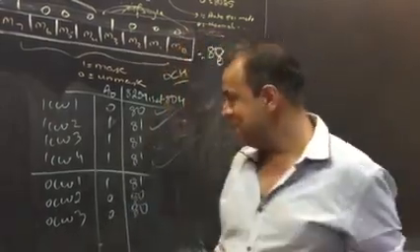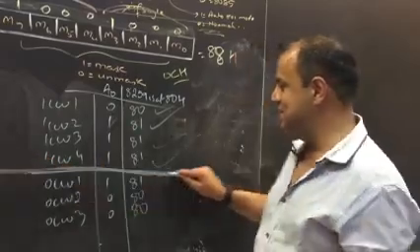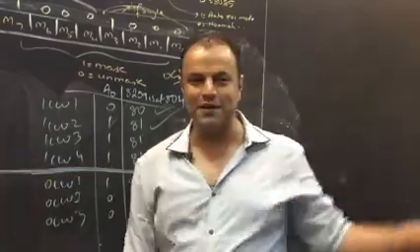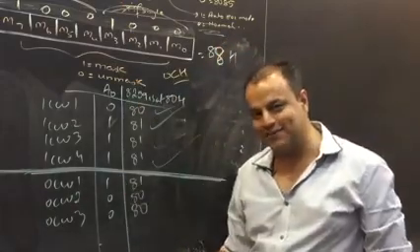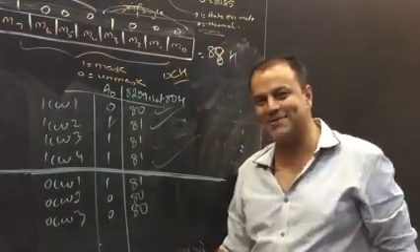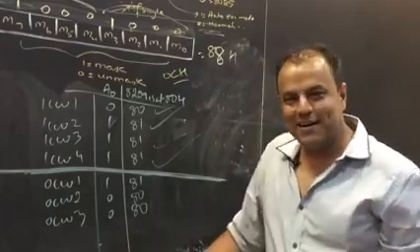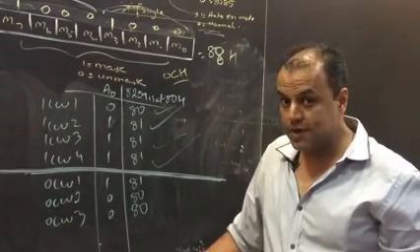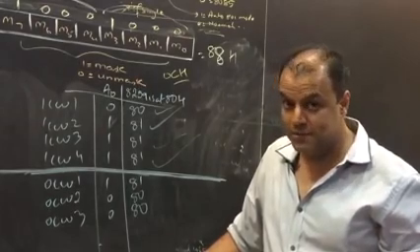Are you clear? Also, once you identified these, ICWs are over. They cannot be repeated. They are out of contention. Now you're left with only 3 commands and you still have 2 addresses to identify them, 80 and 81. OCWs are more tricky. There are no rules on OCWs. They can be repeated. They can come in any order. They may not even be given.